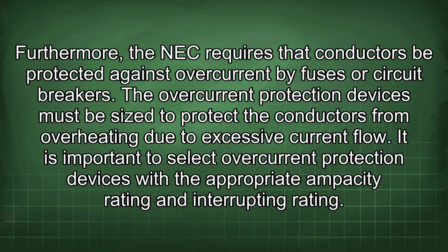Furthermore, the NEC requires that conductors be protected against overcurrent by fuses or circuit breakers. The overcurrent protection devices must be sized to protect the conductors from overheating due to excessive current flow. It is important to select overcurrent protection devices with the appropriate ampacity rating and interrupting rating.